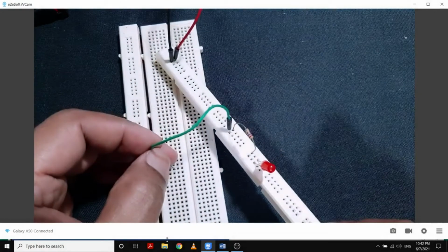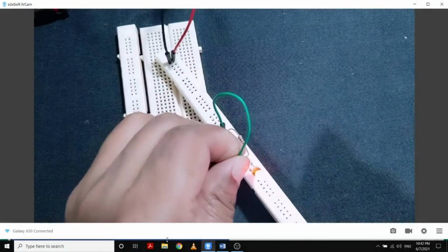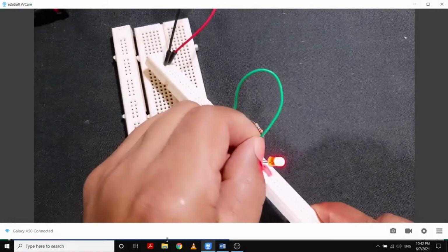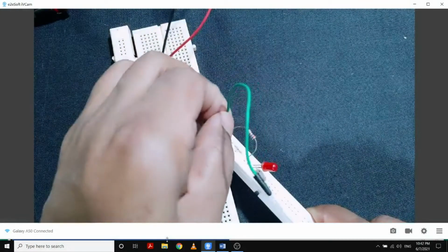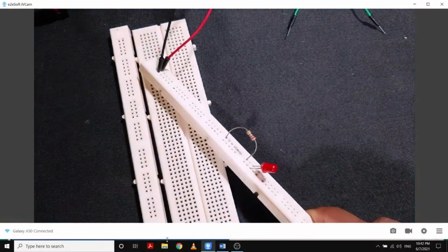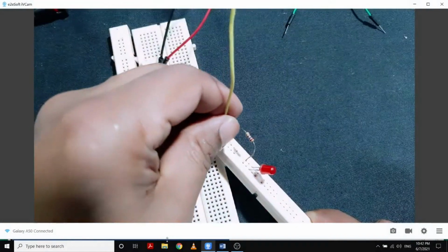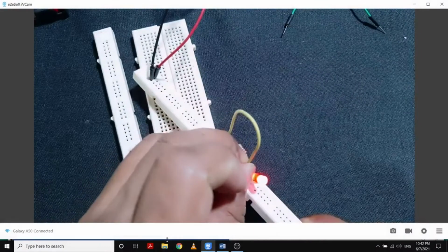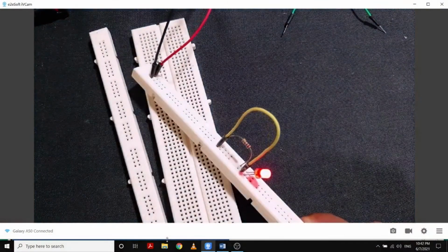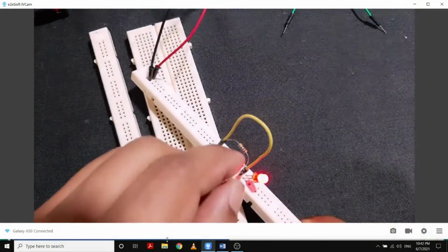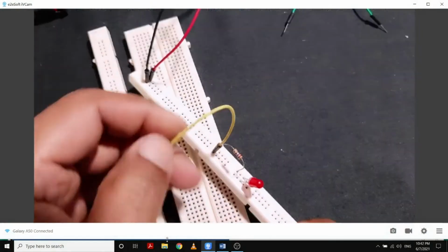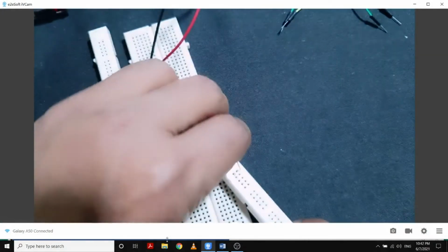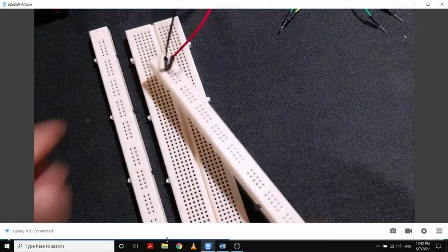The resistor there, and then now I'm going to complete the circuit here. You can see the lighting of the bulb, right? So then you replace this wire, few wires, and check whether all your wires are internally okay, without break, right? Disconnect all the items, and let's try to start our assembly of the circuit, right?